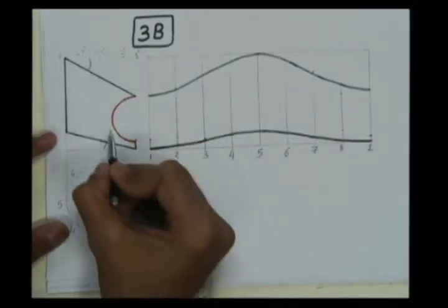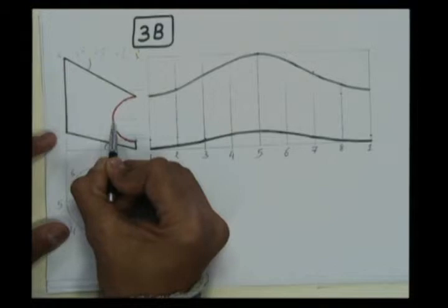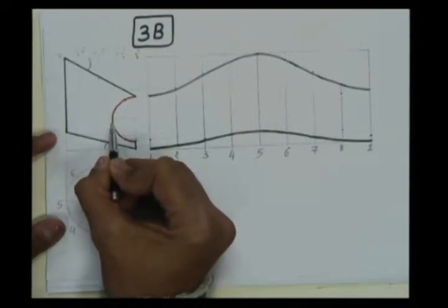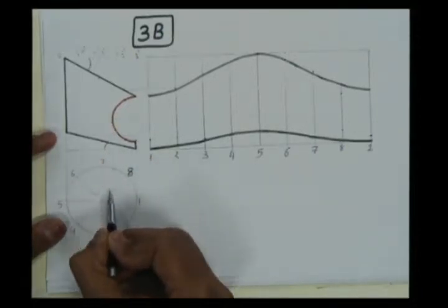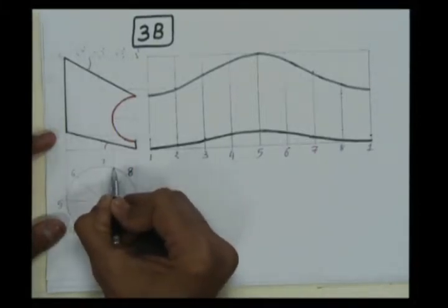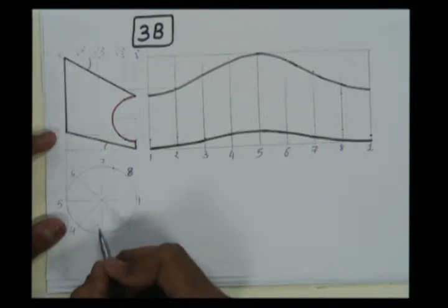Now what about this end point? It is very critical to find the position of this point, and for that let me transfer this point to its true position. So from this point draw a straight vertical line that will cut the cylinder at 2 points. One point is here between 7 and 8 and another point is here between 2 and 3.